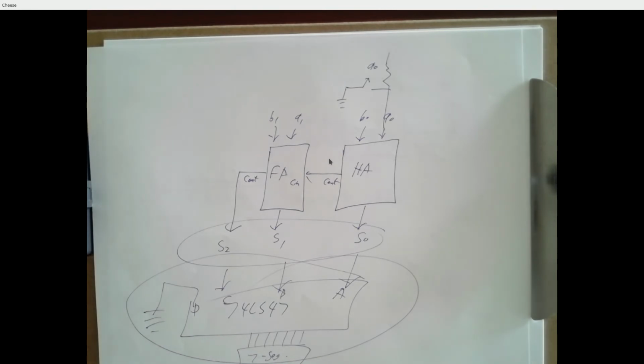So it's a long lab, but you can break it into pieces and make it pretty manageable. One piece, like I said, is just to play with the 7-segment display. That's experiment 1. Another piece is just to play with the 7-segment display and the 7447 and get a handle on how setting those A, B, C, D inputs affects the display. And that's a fun thing to do anyway, as much fun as you can have in the lab at least. It's a fun thing to do because you get to display things.